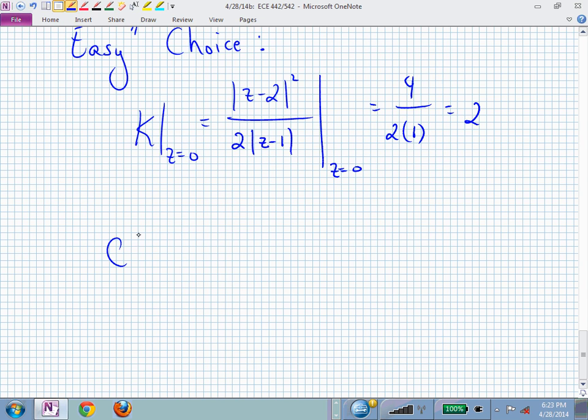And what kind of response behavior are you going to produce with this unstable controller? A deadbeat response, because now our closed loop poles are right at the origin. This controller, it's unstable, but we started with an unstable plant. Now we have a deadbeat response for that choice of gain k.